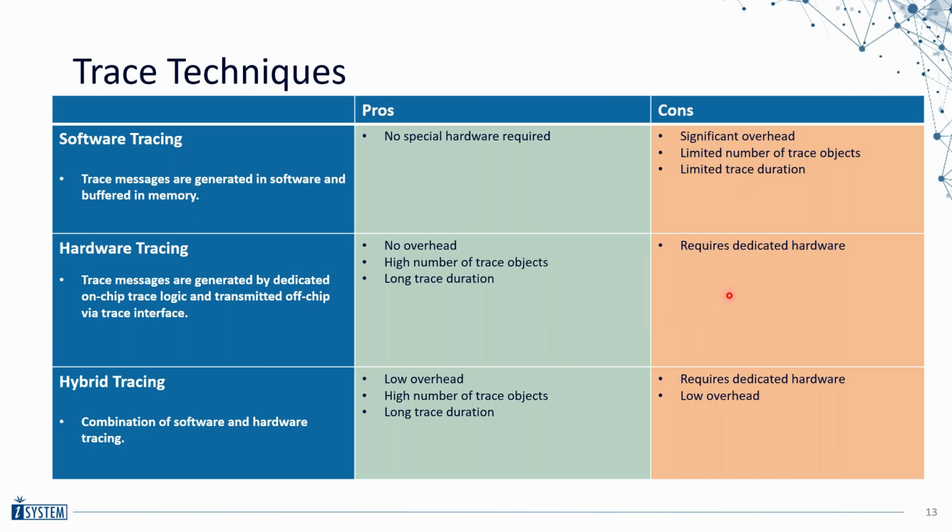Of course, with hardware tracing, you need dedicated hardware. You need the on-chip trace logic, and you need the debugger to interface with that trace logic using the dedicated trace interface. So this should make clear the difference between software and hardware tracing.